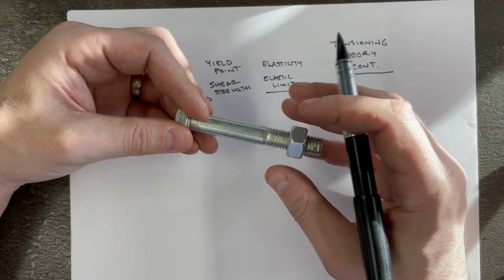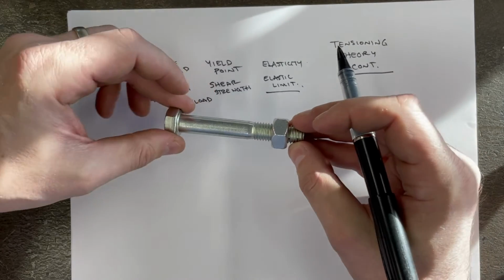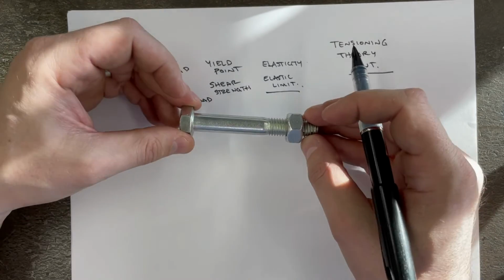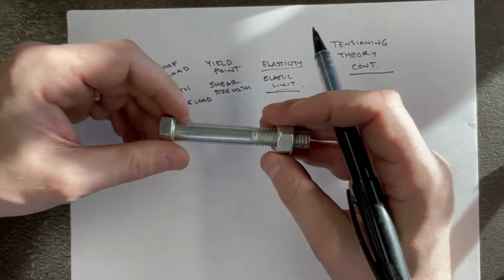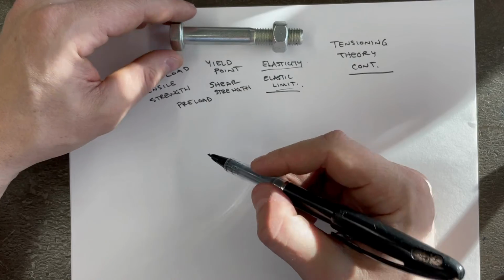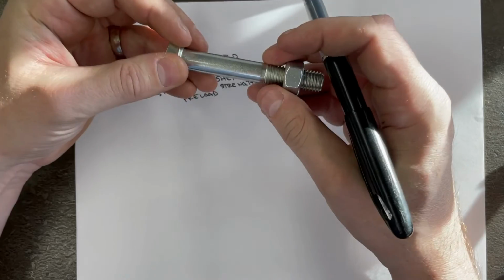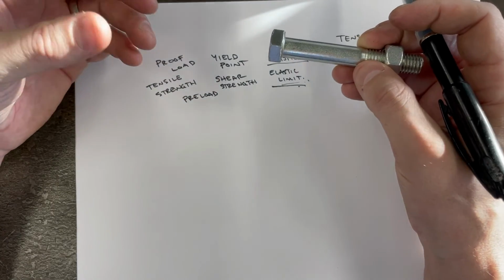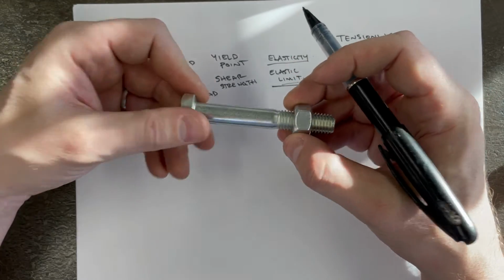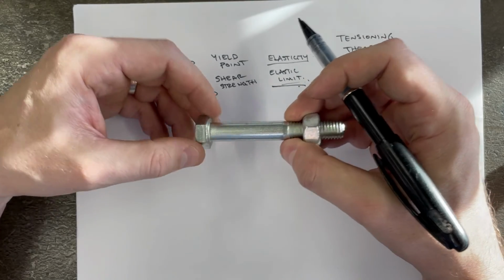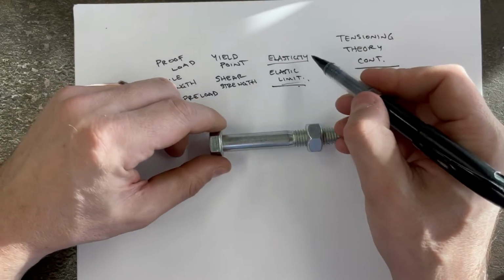So the elastic limit is how much stretch I can put on this bolt before it gets permanently deformed, so that it's permanently elongated or stretched. So elasticity and the elastic limit are two different points. With a fastener, you'll have the elasticity and the elastic limit. If you get into the elastic limit so that it won't return back, that's okay. A lot of fasteners are one-time use, where we're going to use them one time and then throw them away after. Being inside that elastic limit is going to give you the maximum amount of strength of that bolt. So that's the elasticity and the elastic limit.